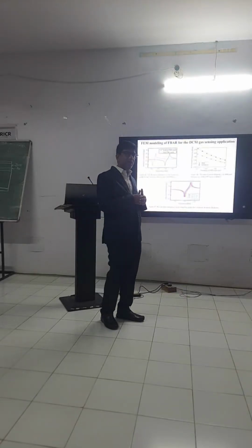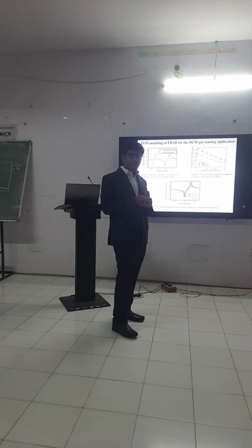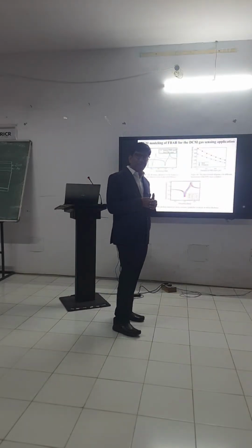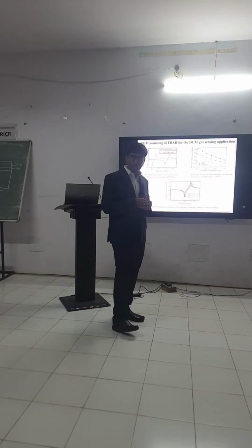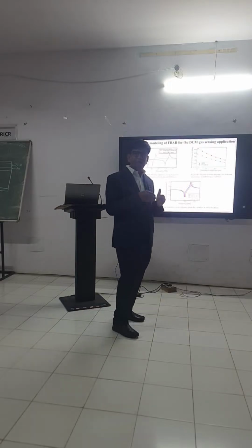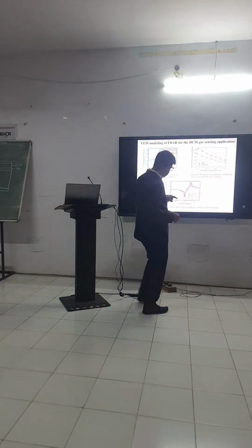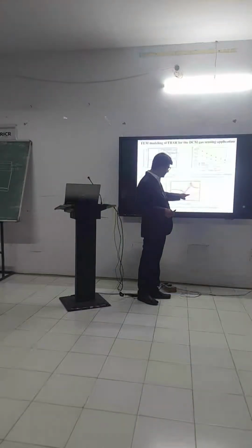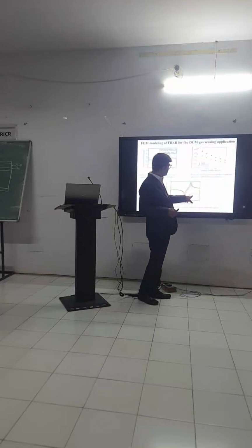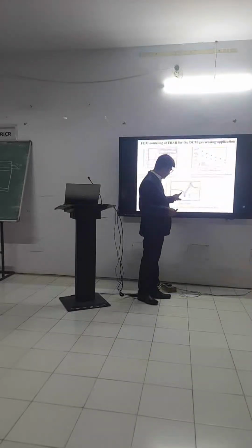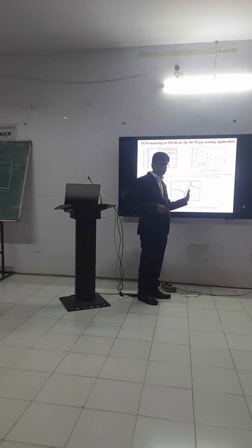For example, I am looking for 1 micron thickness of silicon oxide layer and 0.7 micron thickness of my molybdenum layer, and let's suppose it changes by 5 to 10%. Here you can see, initially we decided this thickness should be lambda by 4. So this is the performance parameter. But let's suppose the molybdenum thickness varies by 10%. What will happen? Your frequency will be increased.